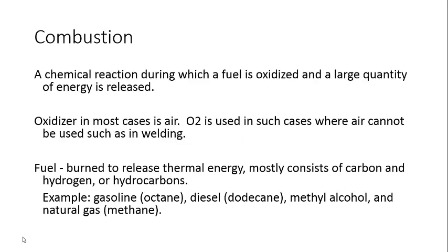Okay, combustion. This is what the chapter is mainly about. Combustion is a chemical reaction during which a fuel is oxidized and a large quantity of energy is released. The oxidizer in most cases is air, and the O2 is used in such cases where air cannot be used, such as in welding. So basically the air is used as a carrier for the oxygen. The fuel is burned to release thermal energy and mostly consists of carbon, hydrogen, or hydrocarbons. So examples of this would be gasoline, diesel, methyl alcohol, and natural gas.